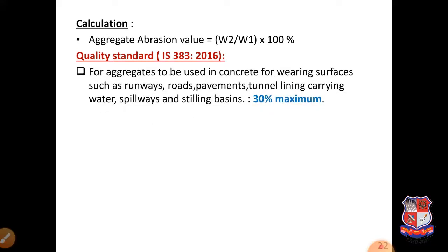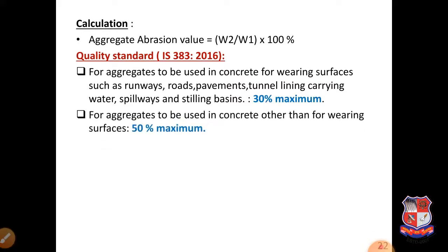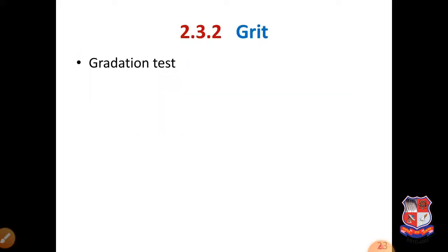According to Indian Standard 383/2016, for aggregates to be used in concrete for wearing surfaces such as runways, roads, pavements, tunnel lining, carrying water, spillways and stilling basin, 30% maximum. For aggregates to be used in concrete other than for wearing surfaces, 50% maximum.